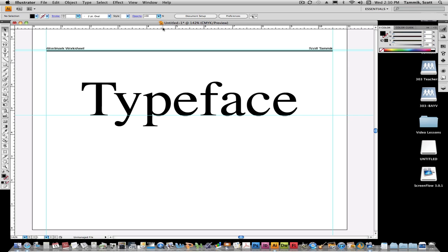So I'll put a guide underneath or at the base of the type, one in the middle here, and one toward the top of the letter T. And I'm going to box in with two more guides on either side so that we've kind of boxed or trapped in that word typeface. Right? We're going to add on a couple of dotted lines or dashed lines now, and they're really easy to make in Illustrator. If you remember, there's a line segment tool, this one right here.